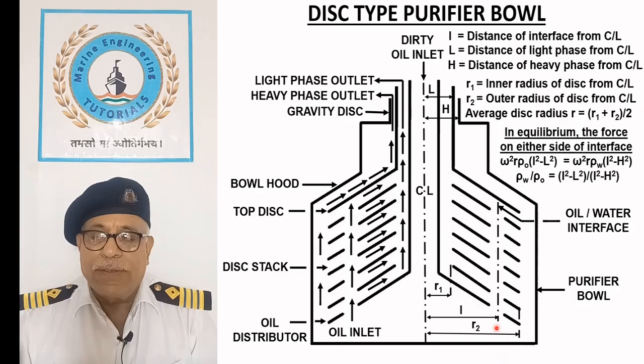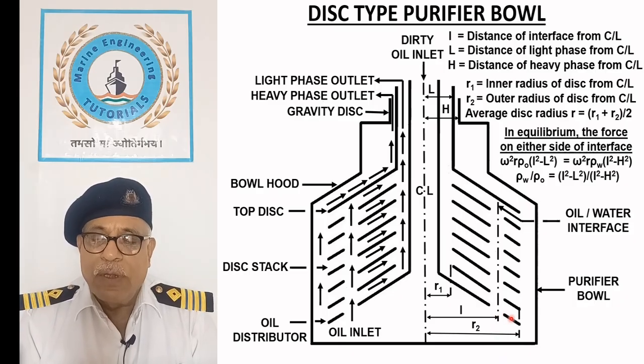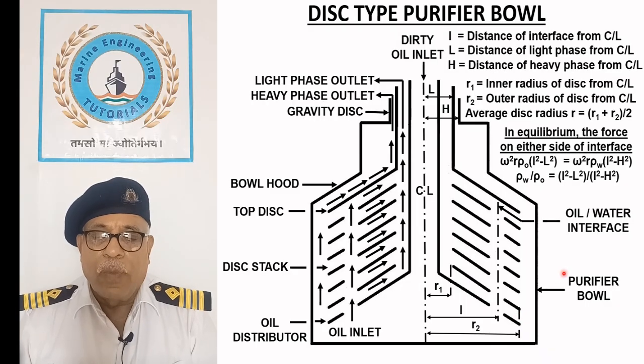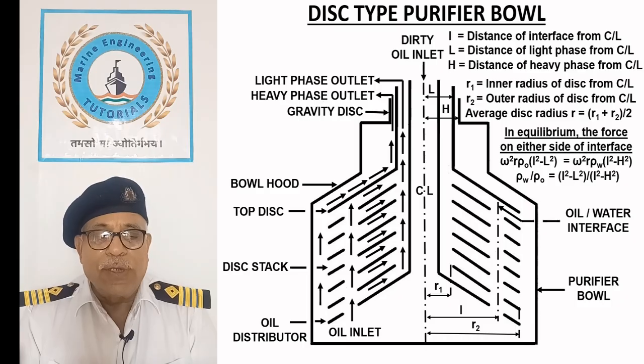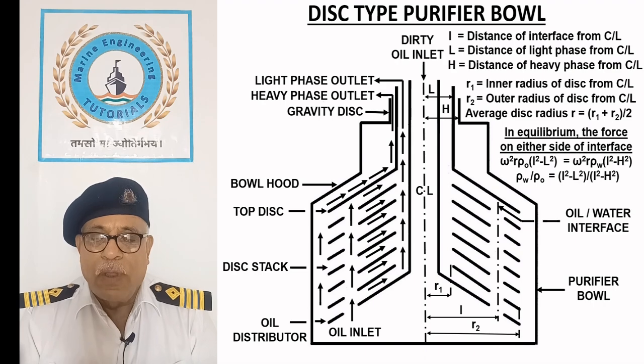If the interface moves outward, oil will be discharged with the water. In clarification mode, no water seal is required. Clarifier discs either have no distribution holes or the bottom disc alone is without holes. In fact, purifier discs can also be used for clarification.